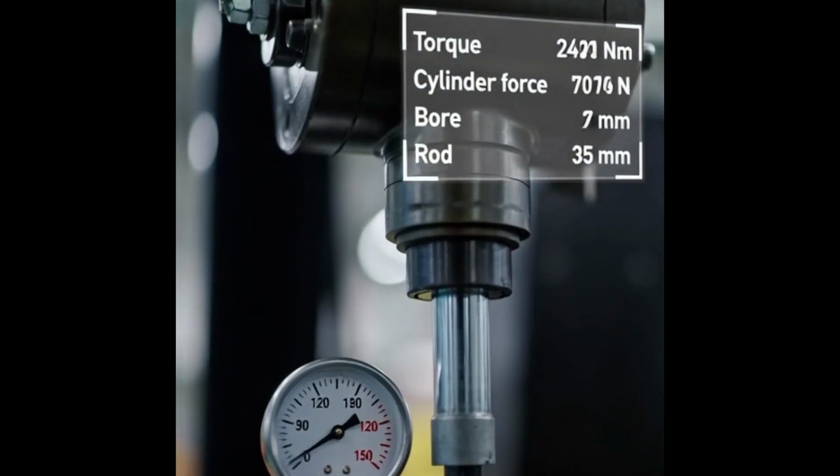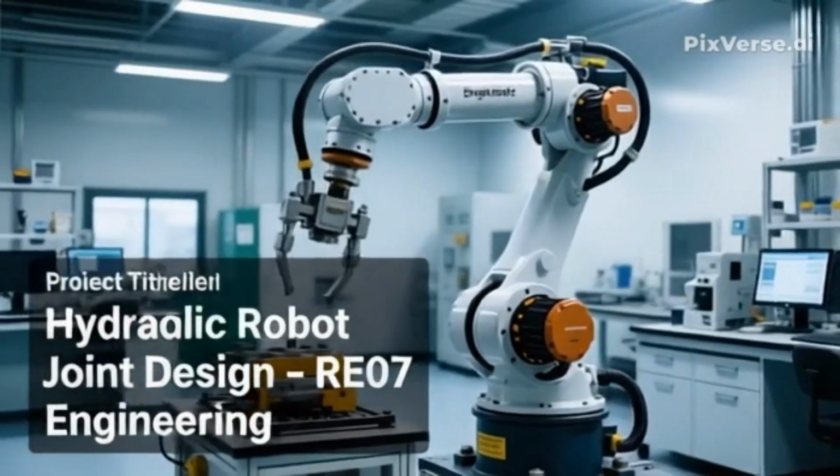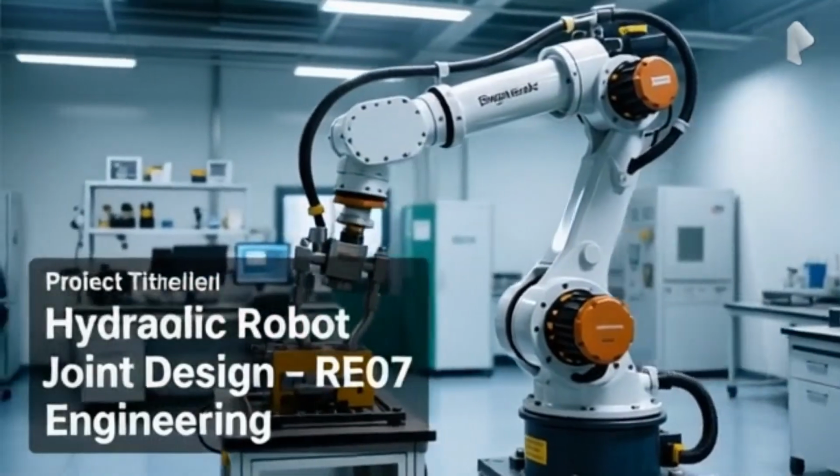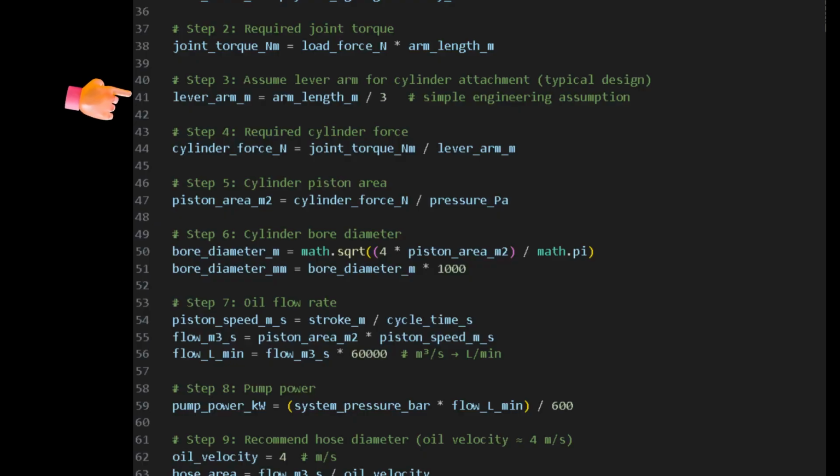Step 3. Calculating cylinder force. Now we connect mechanical torque to hydraulic force. In real robot arms, the hydraulic cylinder is connected to the joint through a lever mechanism. For simplicity, we assume the cylinder lever arm is 1/3 of the robot arm length.